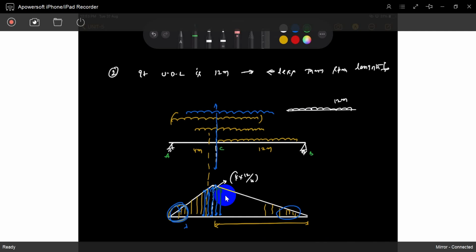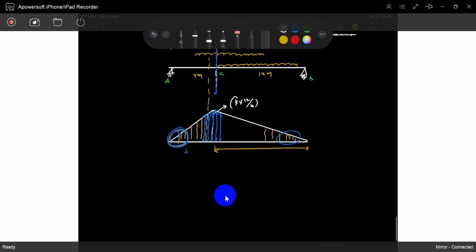Okay, I will give it. I will arrange it, I will say exactly. It is the span ACB. You have to put the load exactly in the ratio of AC to BC. You have to divide the load on the span AC to CB. Then only it balances exactly. It is exactly balanced at point C. Then you will get maximum intensity under the load. Understood? Putting it like this only, you will get the maximum chance. Okay.